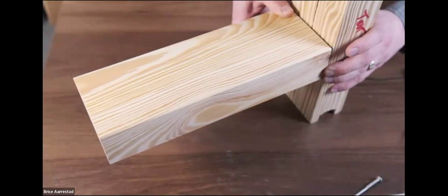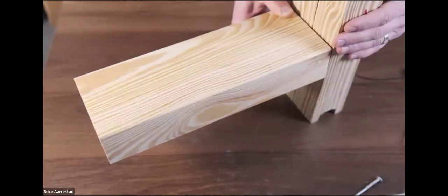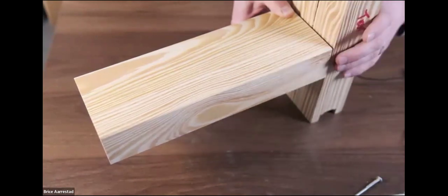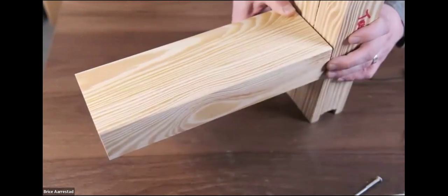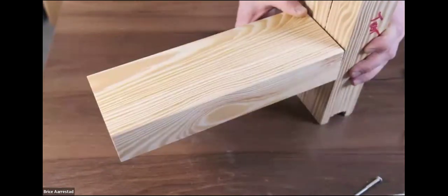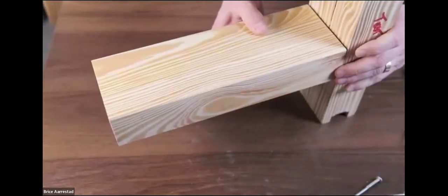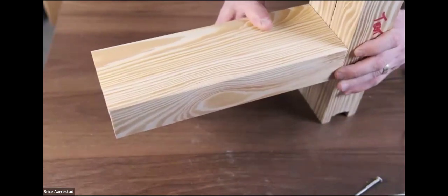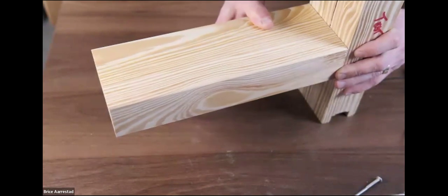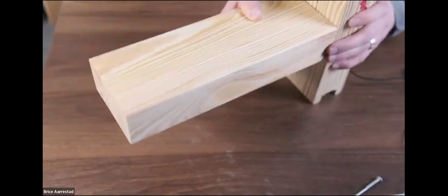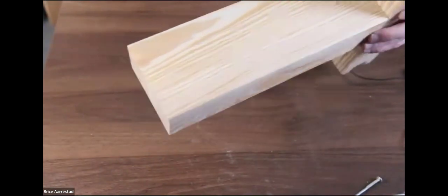We can have all of these be the same depth, but you can also vary the depth for the horizontals. So oftentimes we'll see, if the back member is, let's say, 10 inches deep, you'll still use a 4-inch intermediary or horizontal transom. So some options there. When it comes to economizing the system, reducing the amount of timber is the key. So if we can reduce the number of connections, if we can reduce the depth of the system, that will save money over time.